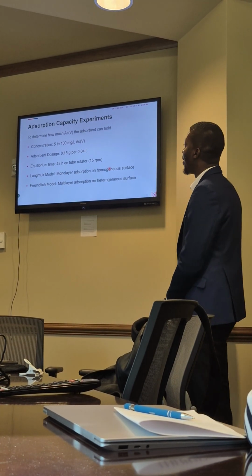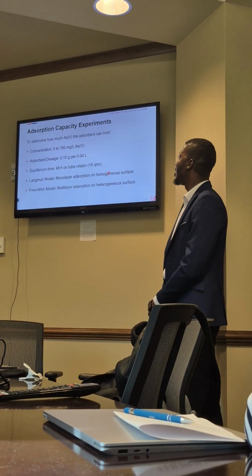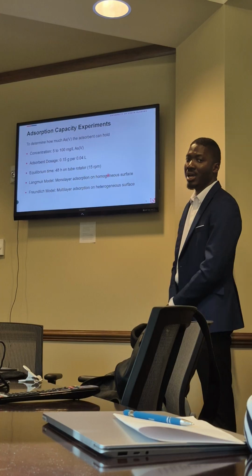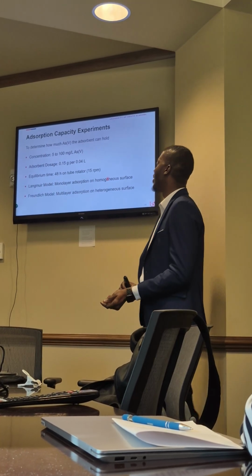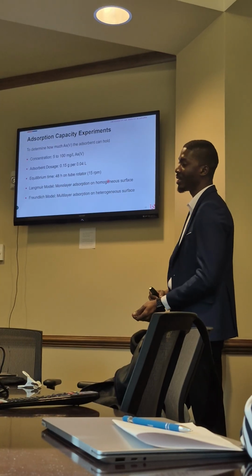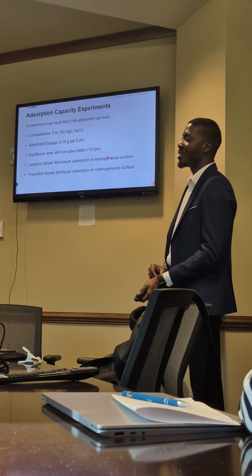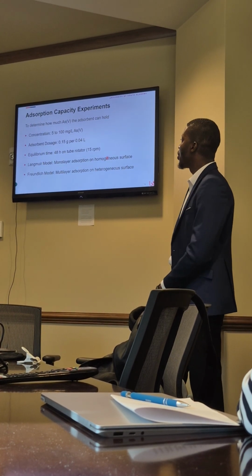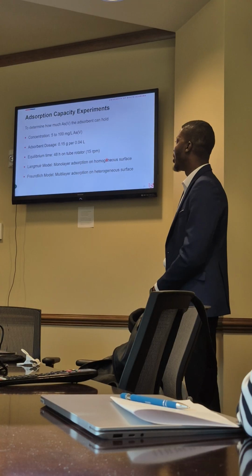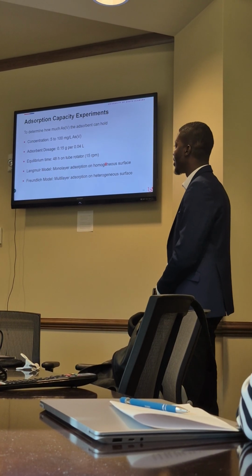So for the adsorption capacity, that was also done to find out how much arsenate our adsorbents can hold. We carried this out at various concentrations from 5 milligram per liter to 100 milligram per liter, where we put our adsorbents in our solution and left it in the rotators until equilibrium at 48 hours. We also used the Langmuir model and the Freundlich model for our adsorption capacity modeling.